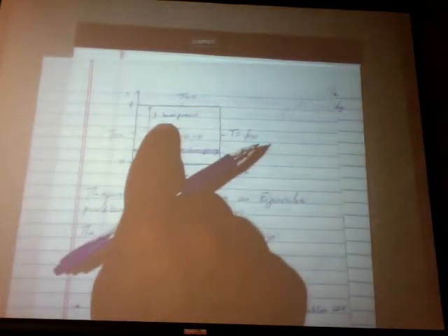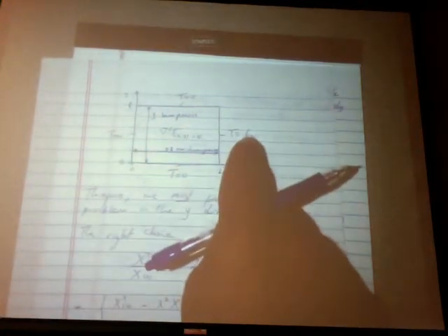It will be an equilibrium condition where the temperature on the borders will be 0, the temperature on the right edge will be whatever this function is, and inside it will be the diffusion of that within the domain. That's what heat transfer is, heat conduction in this case. Okay? The solution in the interior cannot be any greater than f of y or any smaller than 0. It's an equilibrium between all these, driven by the boundary conditions.